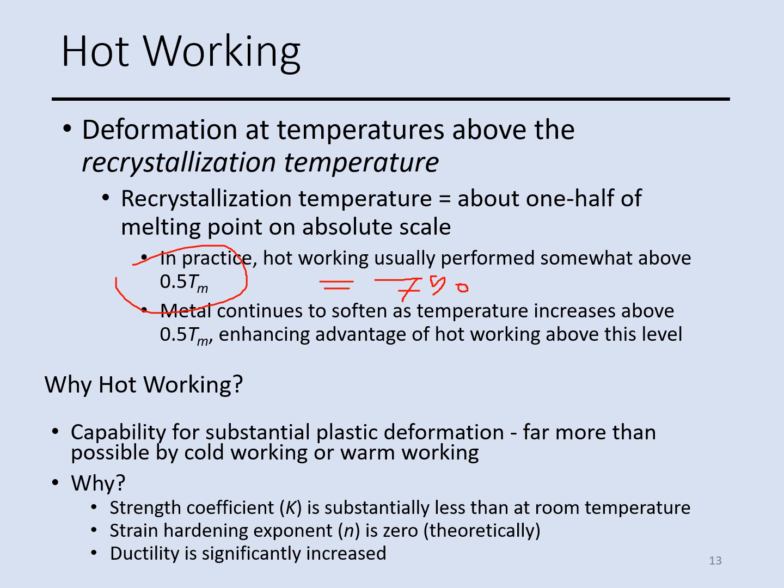And why do we need hot working? Because for some materials, in some cases, if we want to do the process at room temperature, cold working or warm working, we need more stress, more load, because of the plastic deformation. At that temperature it might be too much, and it cannot be handled.